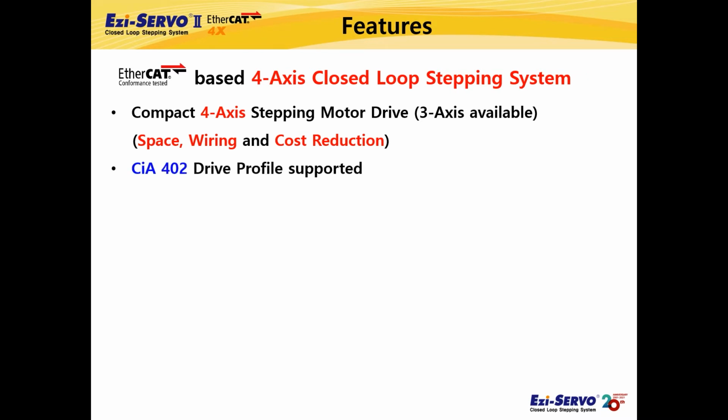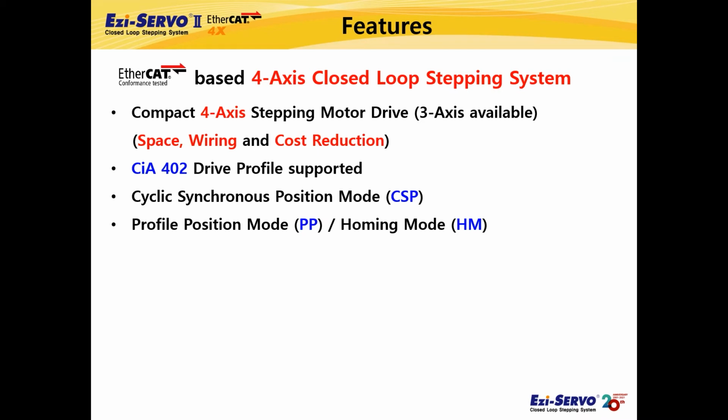It supports CiA402 drive profile, a standard profile for drive motion control. It supports CSP mode that controls the position of the slave, by receiving the target position from the master every cycle. And profile position mode, which is a general point-to-point movement command, and homing mode, which is an origin search command. Also, the minimum cycle time is 0.25 milliseconds. The cycle time is the time required for communication between the master and the slave.